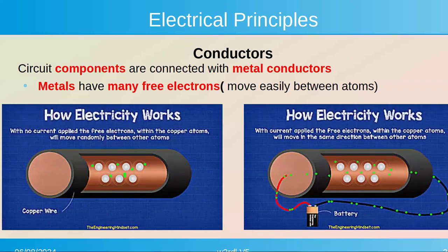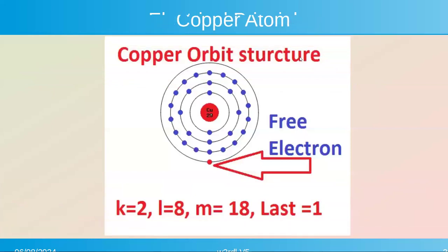Whereas in semiconductors, it's just the opposite. The resistance goes down, which is why in solid state devices, you can have thermal runaway. Because as they heat up, they carry more current. Which is why when you're at Smelly's bar, and your bass is thumping and your voltage drops, your amp draws more current, and then your amp dies and the party ends.